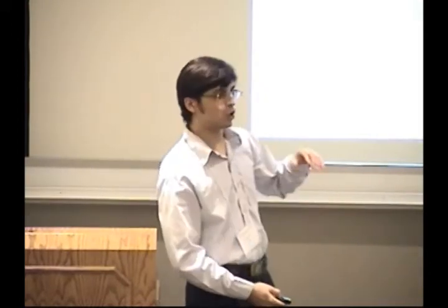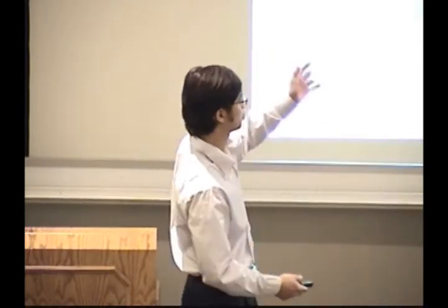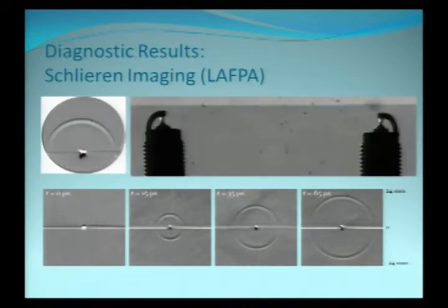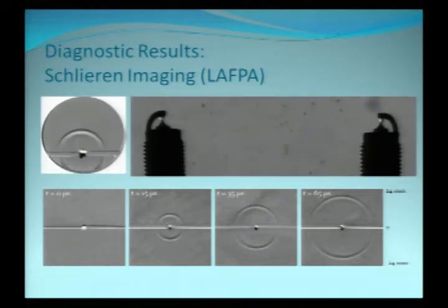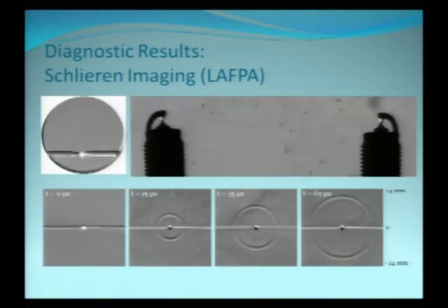So I won't go into all the details of all the diagnostics that we have used because they'll just make it too large. Just show some snippets. So on the top left, you can see 2 electrodes coming in and you can see an arc formation out here. This is Schlieren imaging. And then you can see the blast wave created that's propagating slowly. So this is phase locked averaged images over multiple time samples, which have been then collected together to give you some sort of a movie.